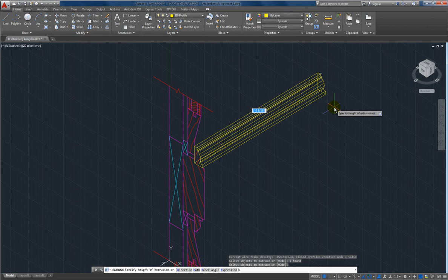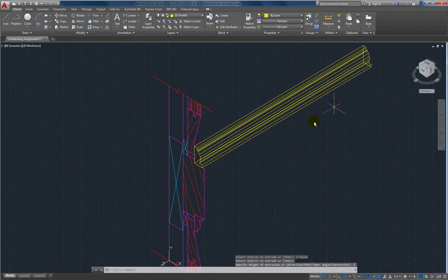Now, if I have stuff that's happening somewhere beyond, just put that at the midpoint, 1 foot. Keep this stuff simple. Okay? Pretty much everything that's beyond is going to be in the same plane. And I'll show you what I mean in a minute. All right? So I can type in 2 feet, hit enter, and that extrudes it 2 feet.